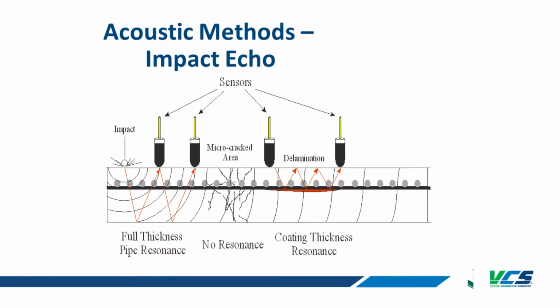Another method that we use a lot to assess quantities of bridge deck deterioration or bridge deterioration is acoustic methods. A lot of people are probably familiar with impact echo, where we make an impact. It's effectively a very fancy chain drag. Chain drag is limited by the acoustic property of what we can hear with the human ear. So we can get fancier ears.